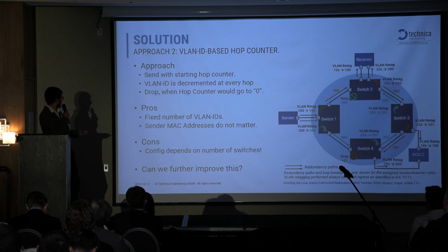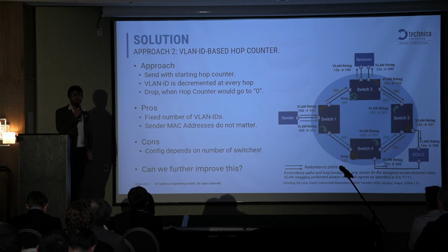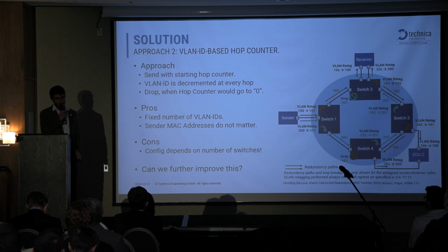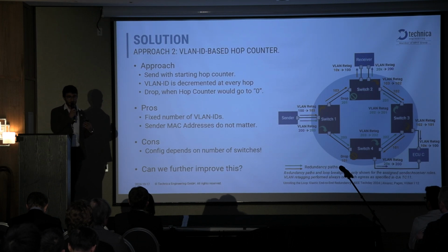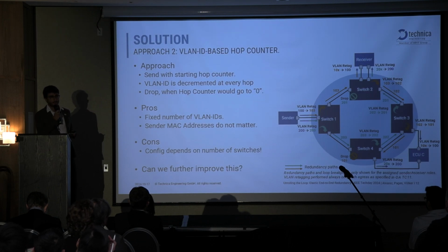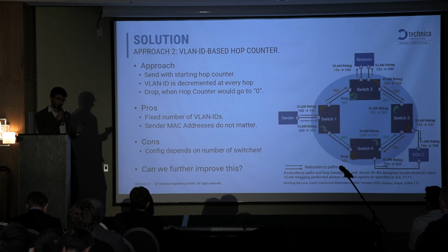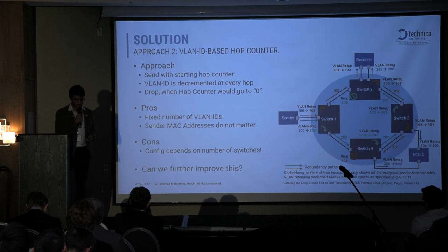And on the other hand, we can state a main disadvantage, that is that the configuration of this system depends on the number of switches. Of course, for this counter, we have designed the first initial value and the last value based on the number of hops of our ring. So if we include new components to this ring, or if we take some components from this ring, then of course these values need to be readjusted in all the switches.